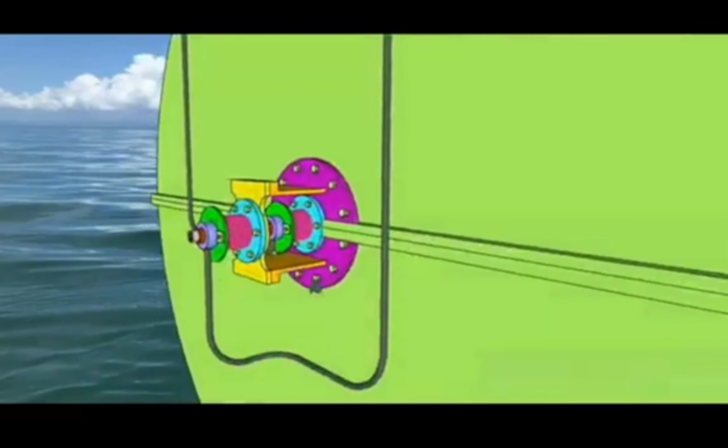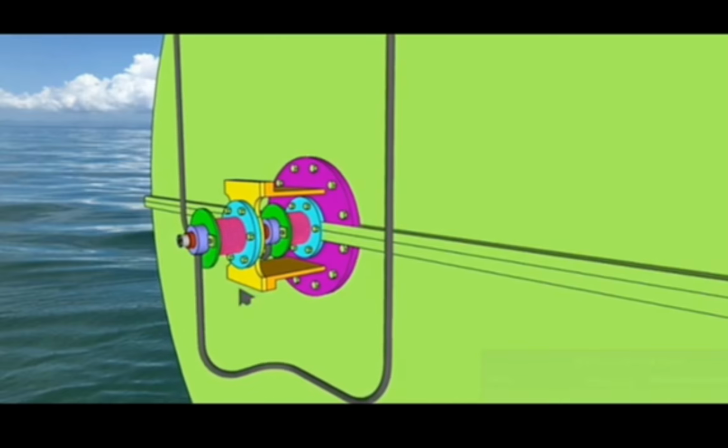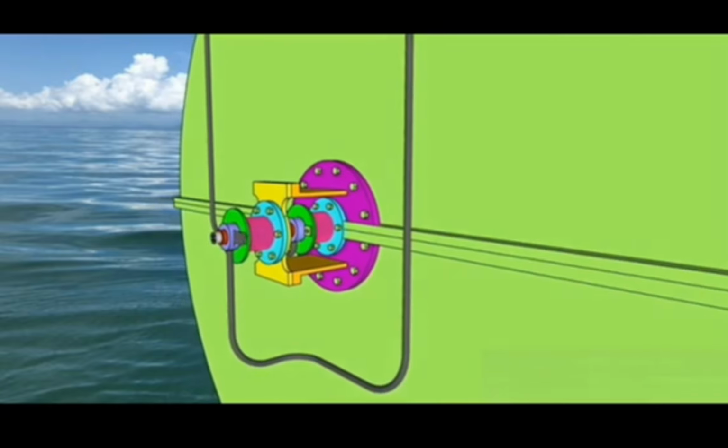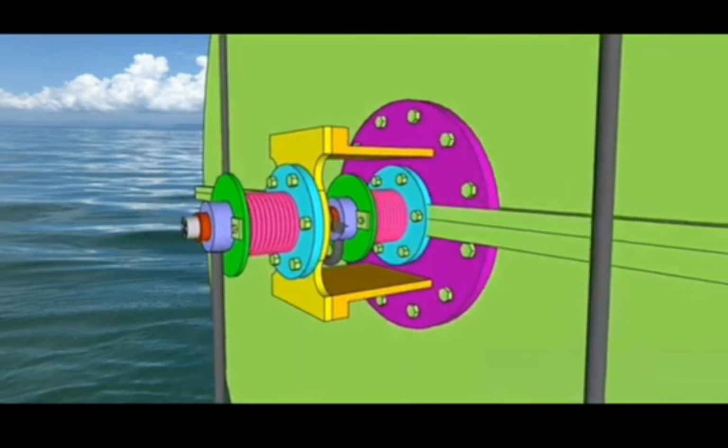And this is another 2 encoders. This is the main encoders. It's fitted forward of the engine. There are 2, given for redundancy. The one behind, the first one, is encoder A, and the second one, the outer one, is called encoder B, and encoder A is exactly fitted on number 1 TDC.